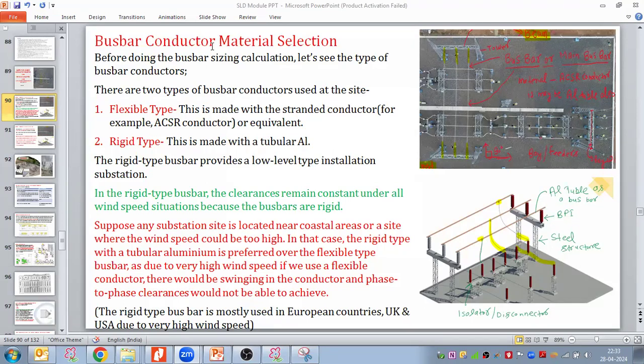Yes, we have to place the CVT in every bay. I have seen in Saurabh's assignment that he keeps the CVT on the bus bar only, so that's why I asked. No, ideally it should be placed with every bay.